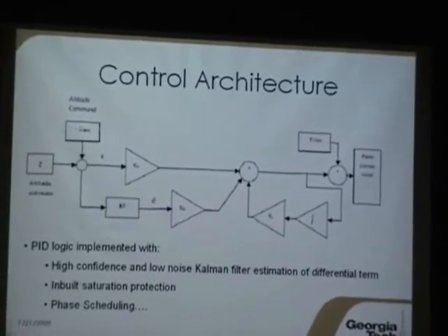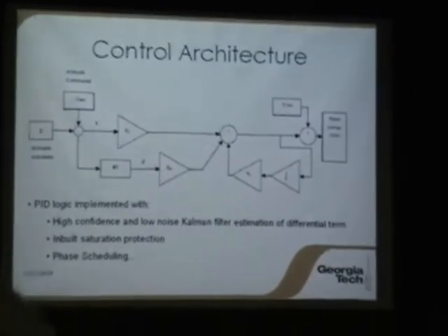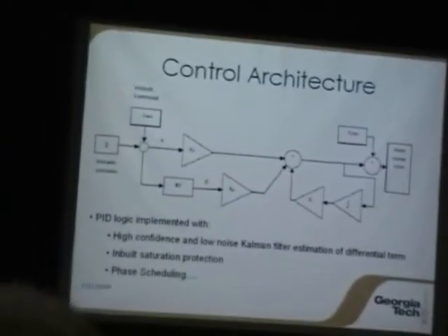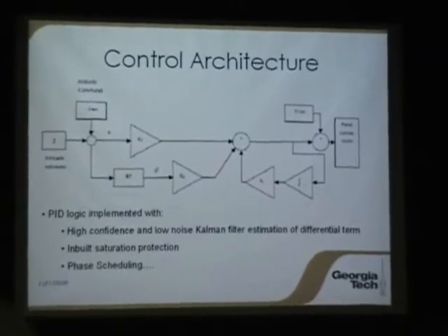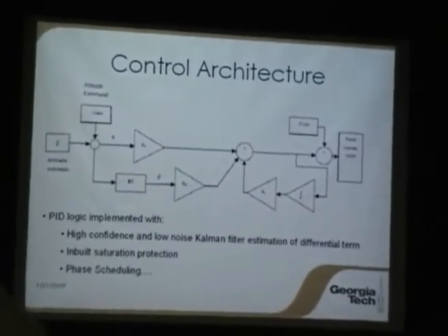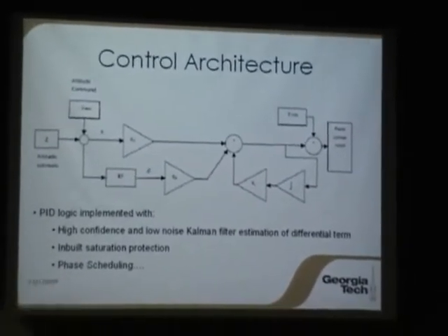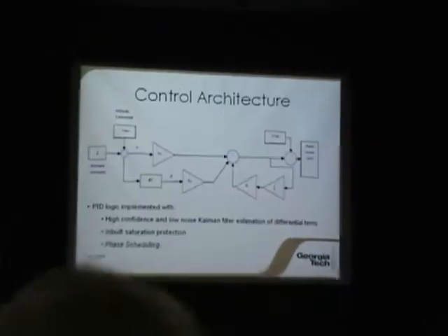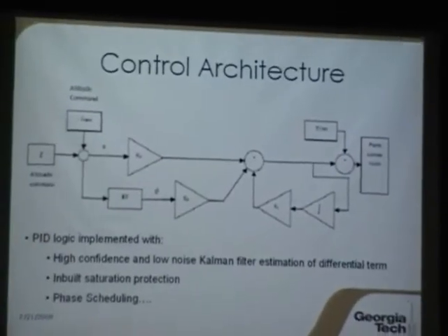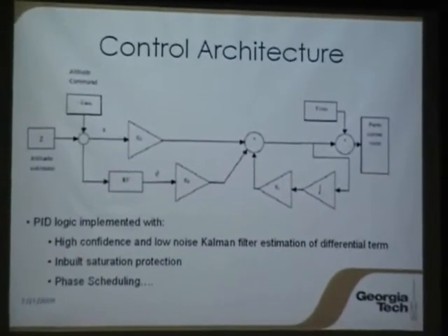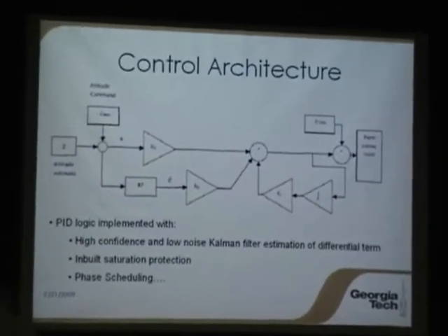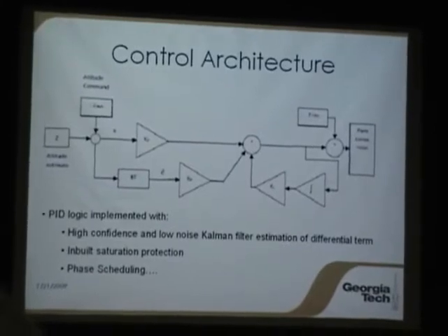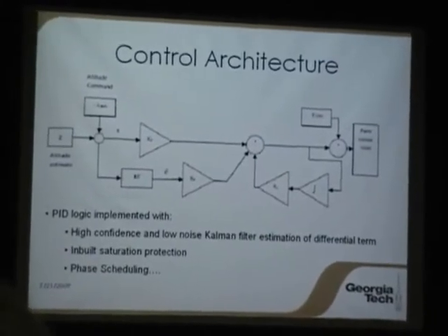So the altitude control basically is a command that is given to the controller by an external source. It's basically a PID implementation, which means there's a proportional part, a derivative part, and an integral part. Now, due to the dynamics of the rotorcraft, it's really important to have a derivative part. Basically, that allows you to have damping in the vehicle. But to have a derivative part, you need to know the velocity, which you don't know. All we have now is position sensors, which are, for example, local range sensors like sonars or IR sensors.